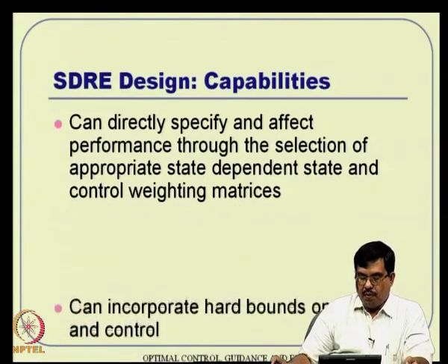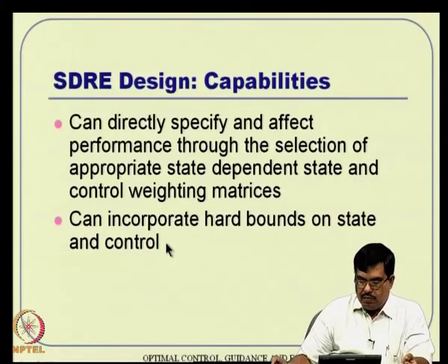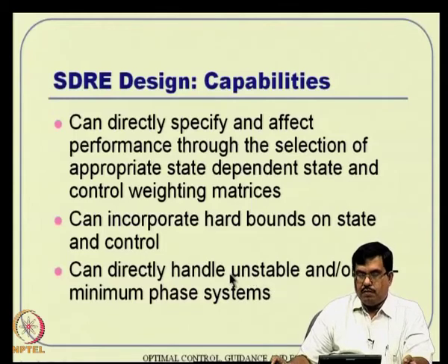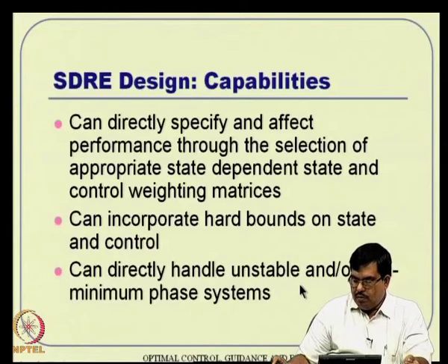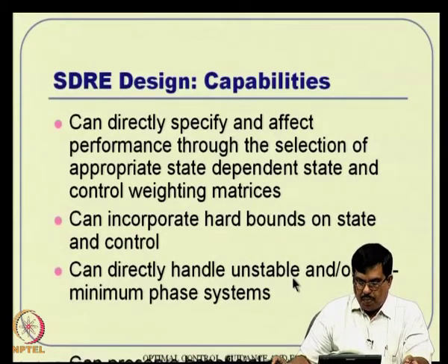There are also extensions that incorporate hard bounds on state and control, so that can also be accounted for. And it can directly handle unstable and or non-minimum phase systems also. That is a generic feature for any optimal control based design, so it also retains that behavior.